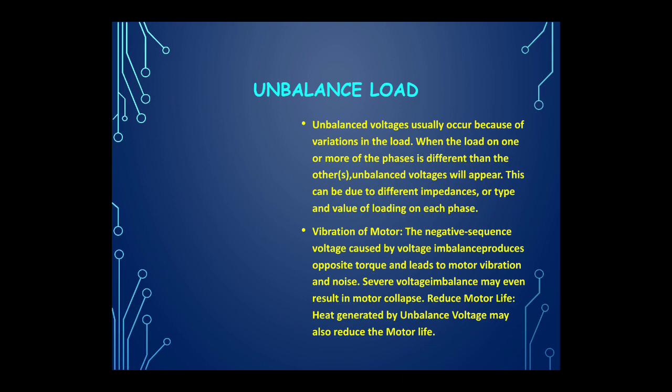We know from our previous discussion that negative phase sequence means the phase sequence is in the anti-clockwise direction. So when a motor is running in positive phase sequence, the field is rotating in the clockwise direction, and if the unbalanced condition arrives, then a negative sequence occurs. So an opposite torque is produced and leads to motor vibration and noise.